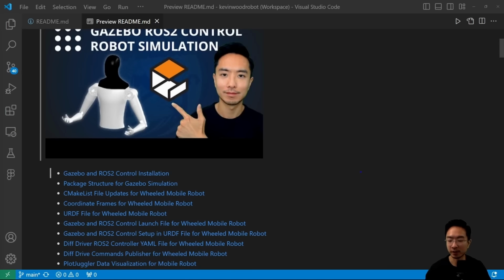So we'll be talking about how to do the Gazebo and ROS 2 control installation, the package structure, the CMake file changes, the coordinate frames, the URDF file, the Gazebo and ROS 2 control launch file, the Gazebo and ROS 2 control setup for the URDF file, the YAML file for the diff drive controller, and the command publisher to send the commands to the wheeled robot, and finally go over some visualization of the data with PlotJuggler.